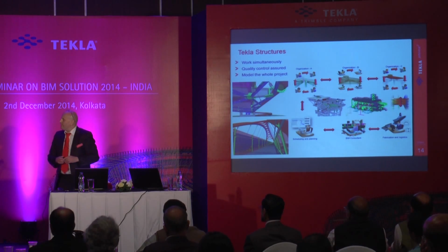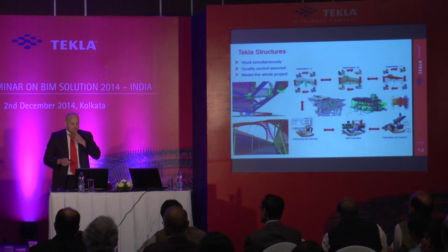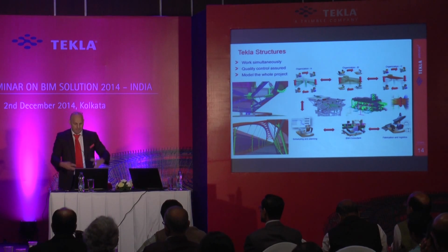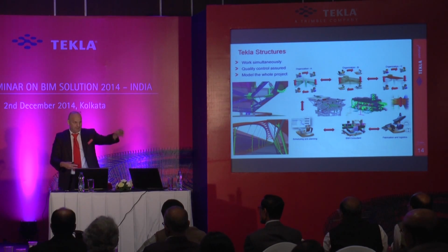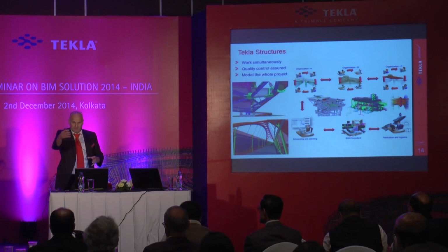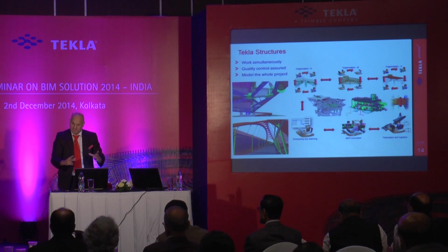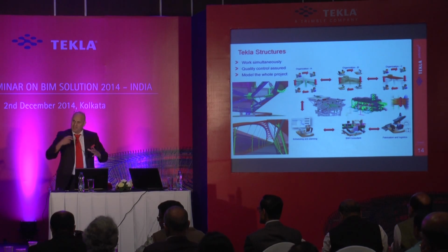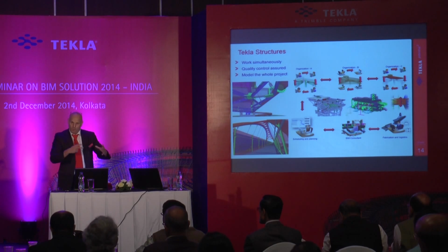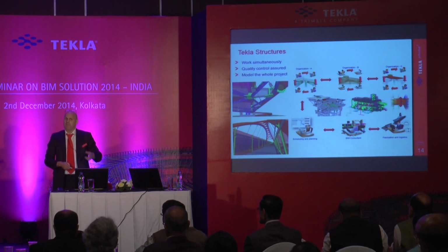The clever thing about the software is it's multi-user. So I can have my model here on my computer, and I can have several detailers working on the concrete, several detailers working on the steel, somebody doing the scheduling, and they're all working on the same model at the same time. These can even be in different offices. Any changes I make, you will see, so everyone's working on one real model at the same time, not an export-import, but a real model, real access. That's a really important part, and it makes Tekla kind of unique in how it works.